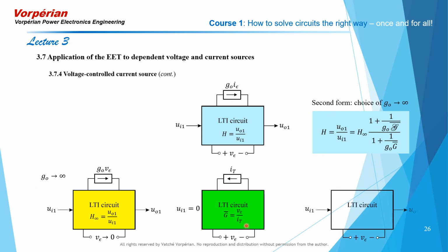So this is the same as before, and likewise the null inverse gain computation is exactly the same as before. Same result, that expression doesn't change. The expressions that you obtain for G bar and script G bar are the same in this case and in the previous case. And with these computed, you can compute the full transfer function using this form of the extra element theorem.